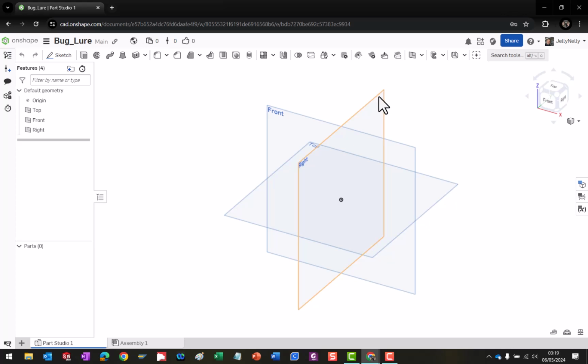So left click is select. So I can select different things with left click. In this case, I've selected all 3 planes just by left clicking on them each once. Clicking in blank space will deselect them. Also, right clicking and then selecting clear selection will deselect items.